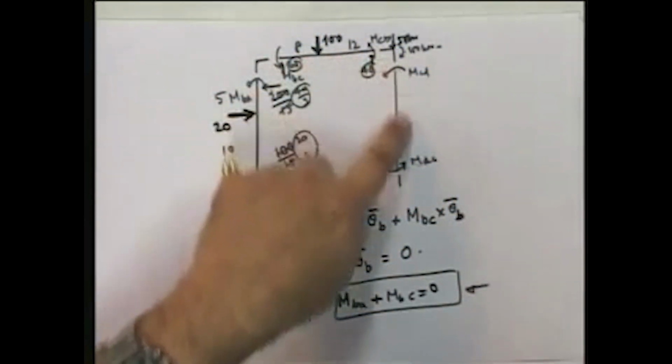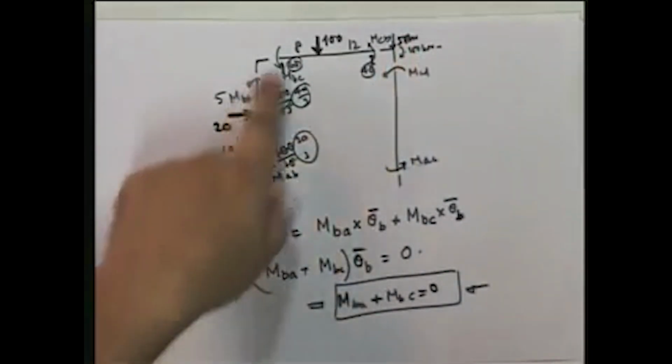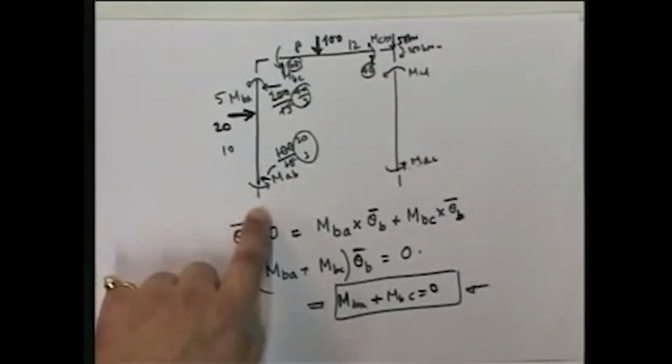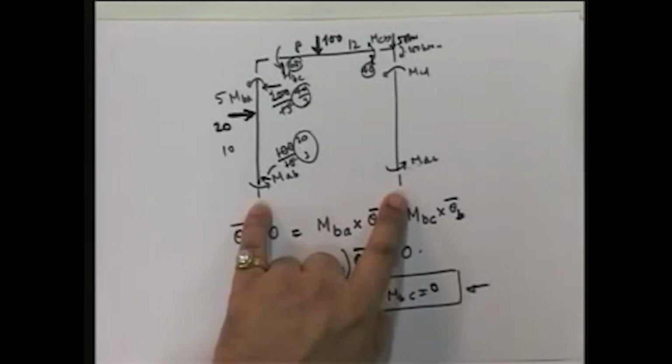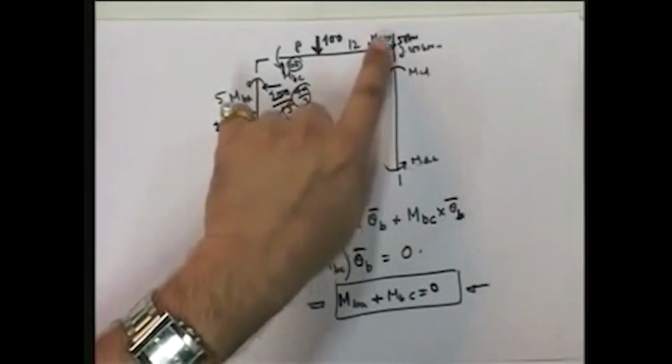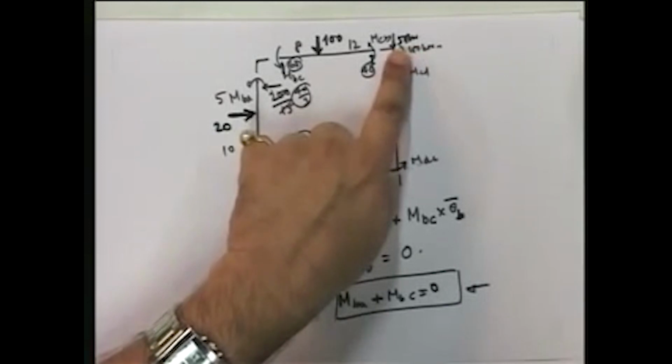Good morning. I'm continuing my earlier lecture. Just to review quickly, I was using the method of virtual displacement to generate the equations, and these are all the internal forces and these are the external loads to which I'm going to apply it. Note that the support reactions don't matter, because the supports never move, so the work done by all the support reactions is always zero. It's only the internal forces and the external joint loads which do any work.